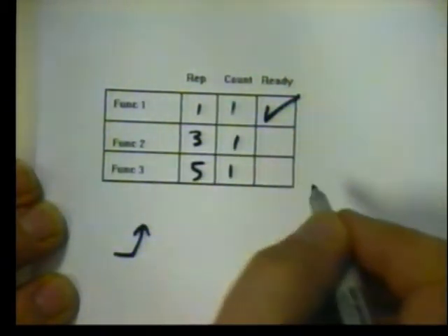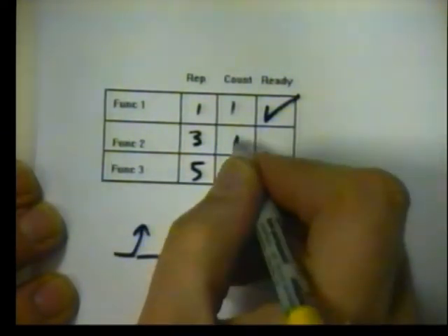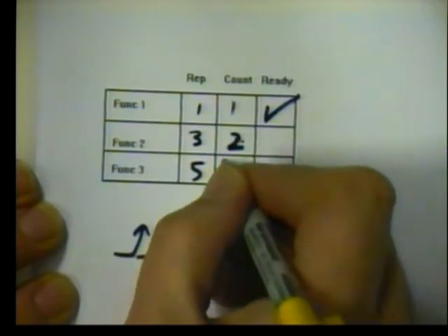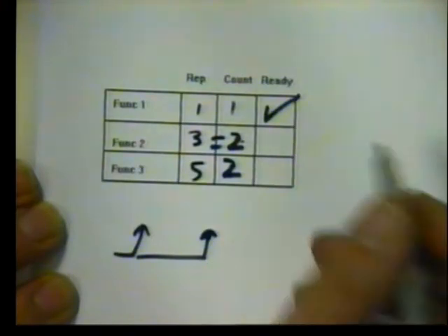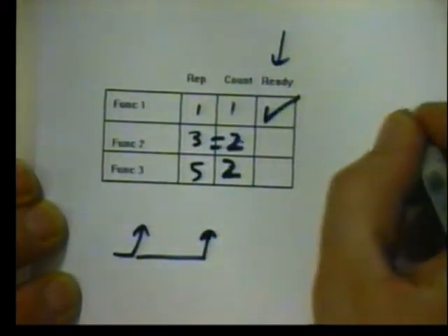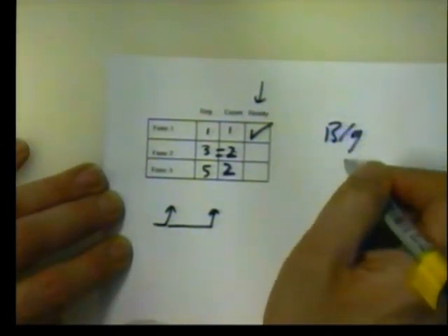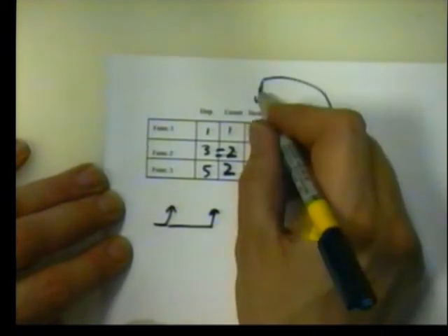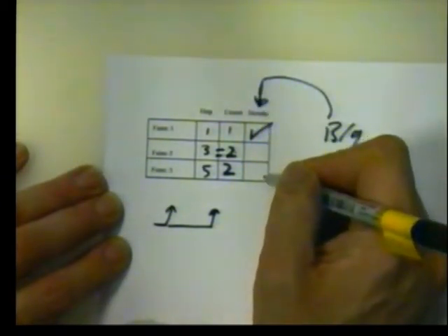On the next interrupt, then that would go to a 2 and that would go to a 2. Only when that equals that would that be signalled to be true. Now this in fact was our semaphore. The background routine, every time it had finished doing what it was wanted to do, it would go and look at this table and say, right, are any functions ready to run?